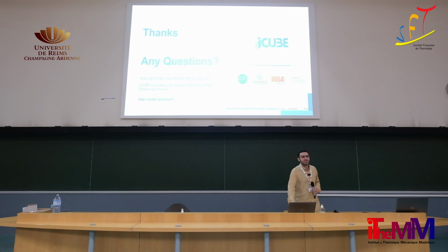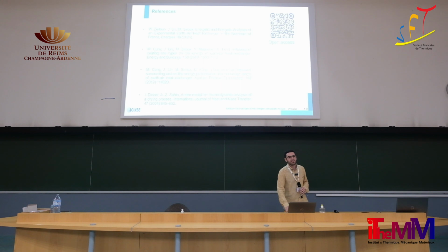Albert Hauck from heat exchanger company Hauck. Why did you use air and not water? So mainly there are different types of geothermal systems, and our system is using air because in France, it is obligatory to have air ventilation inside the building. So we can pass the air through the system before passing it into the air handling unit, so that we can decrease the energy cost for heating or for cooling. So it's mainly an air-based system for air ventilation.